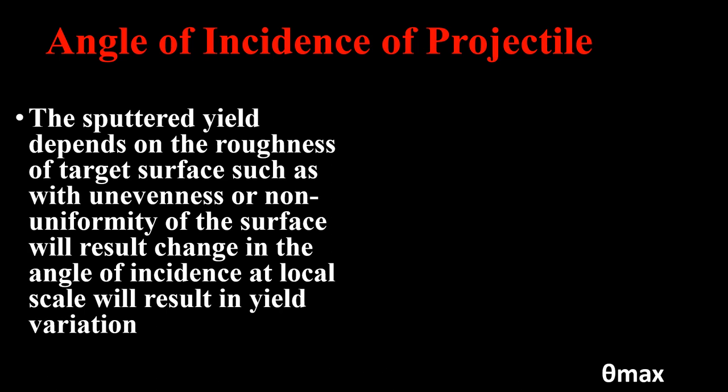First, the angle of incidence of the ion when it is coming toward the source material is different, okay? If the source material at different points has a variable angle, the incident ion will strike the source material at a different angle. So the angle of the incident ion is changing on the surface of the source material, or precursor material.